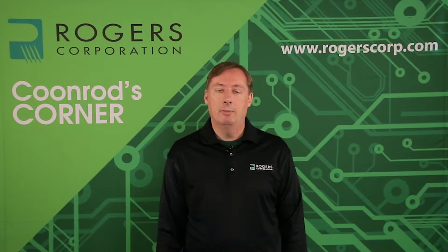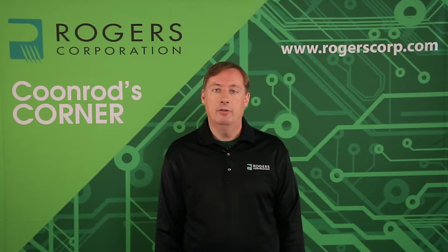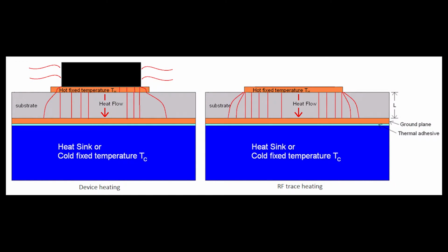So I've shown a very simple drawing here of these two different scenarios just to explain them in a little more detail. The drawing on the left is the same circuit again. It's a microstrip transmission line bonded to a heat sink, and on top of it is an active device generating heat. Some of the heat is radiated off, and some of the heat is in direct contact with the signal plane, so that means the heat has to transfer from the signal plane to the ground plane down to the heat sink below. And that's one scenario for thermal management.